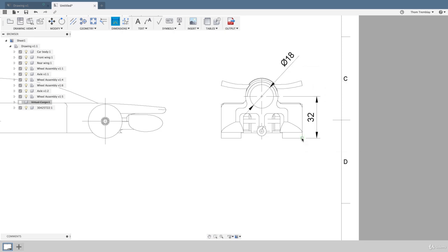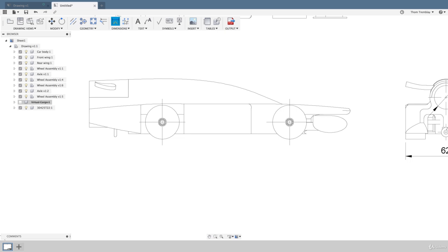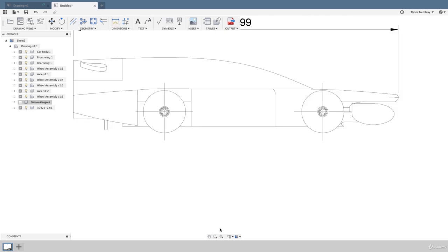You can also go point to point and use the general type of geometry that's on the screen. Here, we'll do an overall length, selecting 2 points. Initially, I get what would be described as an aligned dimension. However, I'm able to move my cursor to get a horizontal dimension. We can continue to apply any detail dimension we deem necessary to get our drawing view created.